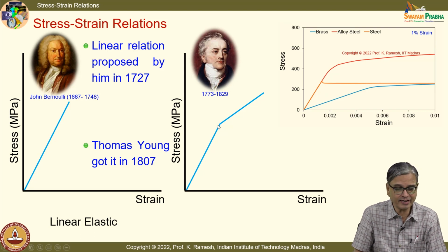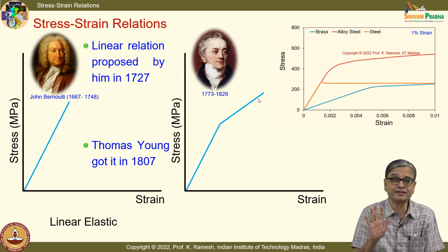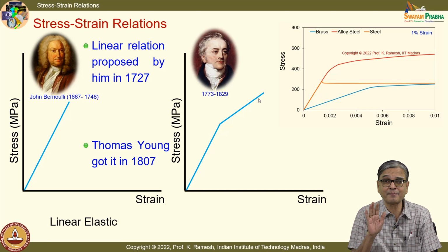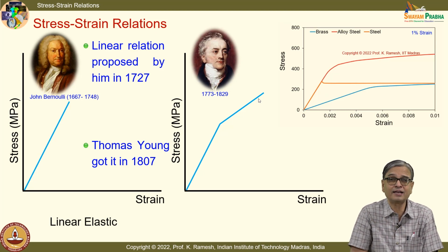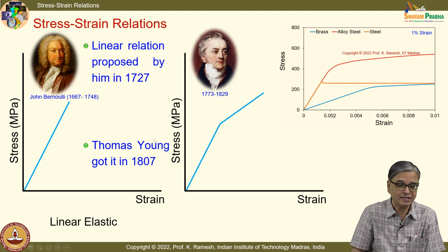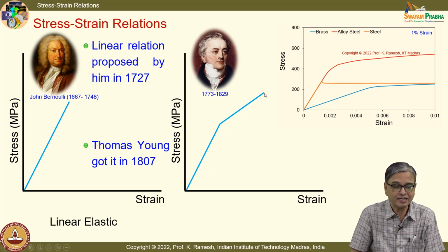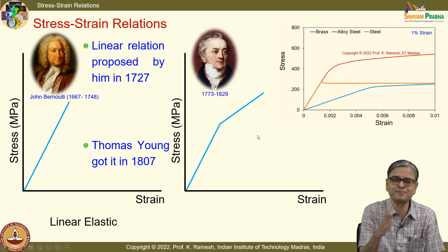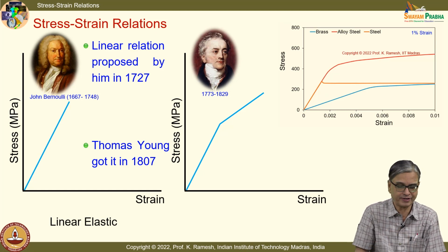Even if you have a straight line for elastic and another straight line for plastic behavior, the mathematics is backbreaking. Please understand, it is not simple. From a mathematical perspective, it is not a simple task at all. Even when people do finite element analysis where the computer faithfully reproduces whatever input you give, only if the modeling is right, you will get good results, otherwise it is garbage. Even there, if they have to model some material behavior, they would do linear elastic and change the slope to model some aspect of plasticity, not all aspects of it.